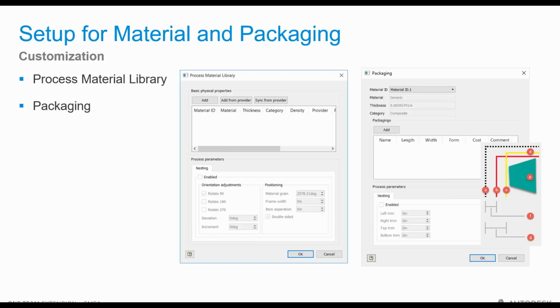So basically, the idea of creating the material library for yourself in a nesting environment would be to define those sheets, to let the nesting tool define those sheets individually. So you could have different materials, same thickness, so they would all come onto the one single sheet. That's how smart the software really is.